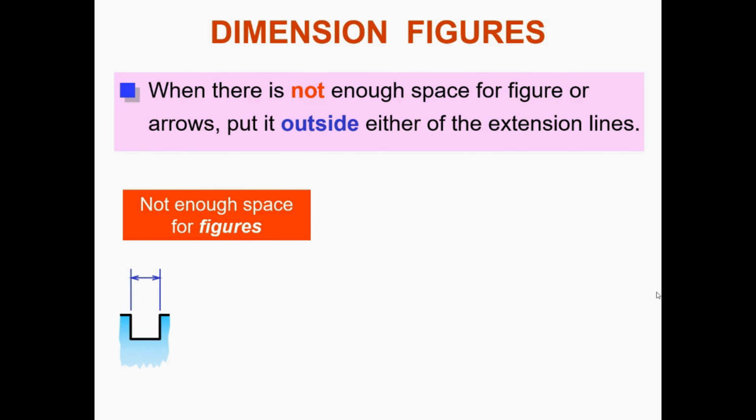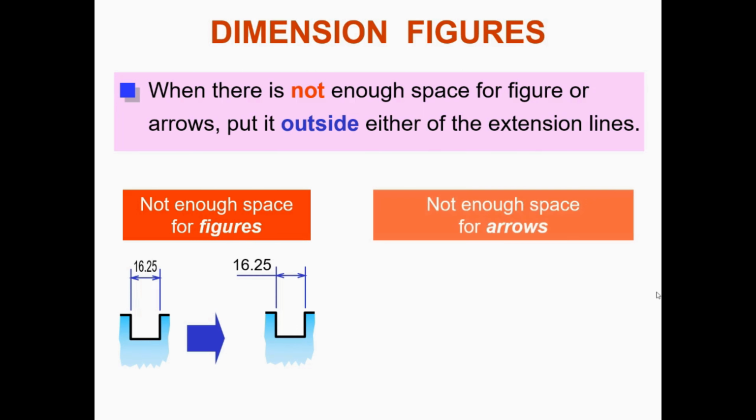But in computer aided design, the software has its way of creating and bringing a dimension for you irrespective of how small the size is. So this is helpful for those who are learning technical drawing. In case you have a drawing that the space is too small, do not squeeze the dimension figure in between the extension line. Always you have to use this approach. You would have to bring the dimension figure outside, and so you leave the space in between there.